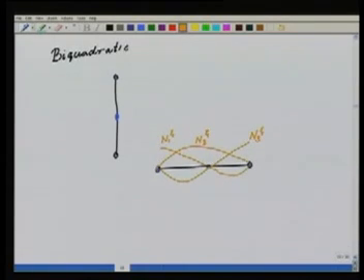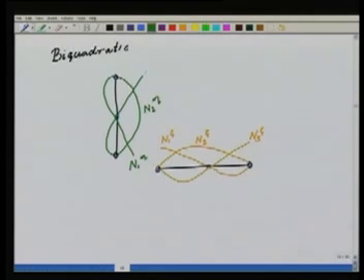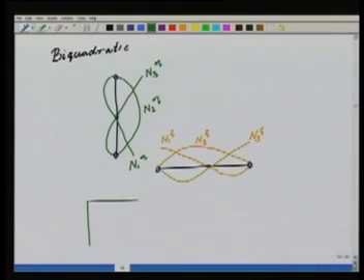On the eta edge, I'll similarly define n1 eta, n2 eta and n3 eta. So I have 3 functions on each edge, so I should have now these 9 functions defined on the master element with respect to these 9 points.